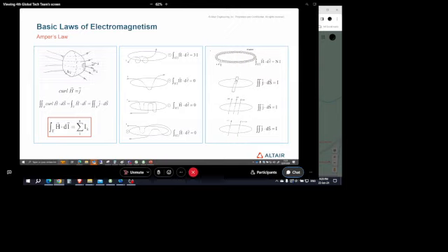So when you supply a coil, you are going to create a magnetic field. And this magnetic field created by this coil can be really complex because you have three phases and each phase is distributed on the number of turns, right? So we need to compute the shape of this magnetomotive force created by this one phase. And this is done thanks to Ampere's law.